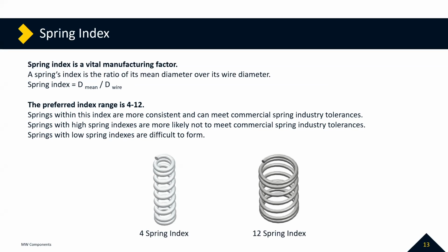It's hard to hold something that's enlarged so much that it's unstable even in the free state. So typically, in a case where the index is that large, you need to either cradle the spring as it's being made or have some type of support there so that the spring as it's being formed stays away from any potential movement. But it can be made. It's just one thing you need to consider in the design of a spring itself.